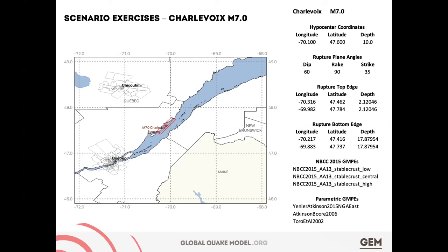In theory, could it define a distributed slip instead? No, not in OpenQuake. That's not a feature, but if you did that in another program, or just wrote your own script to calculate the magnitude from that, then you can use GMPEs that take a moment magnitude. But in the simulation, I expect the PGA to also depend on the location and where the maximum slip is. If you can convert it to a ShakeMap using the USGS tools, then you would be able to import a ShakeMap into OpenQuake. It doesn't have rupture kinematics and these types of fault styles, so that's where you consider the rupture without considering the details. It doesn't consider rupture dynamics.